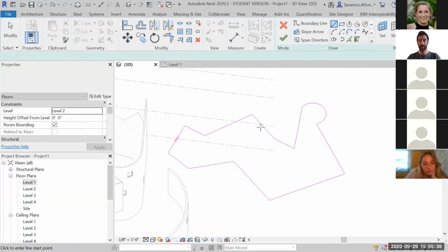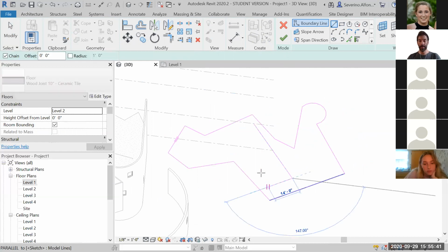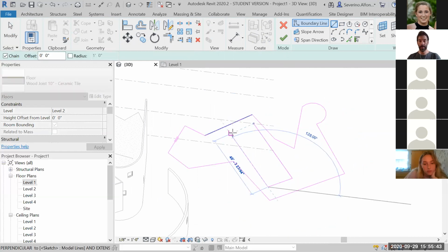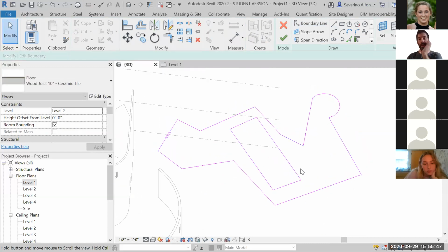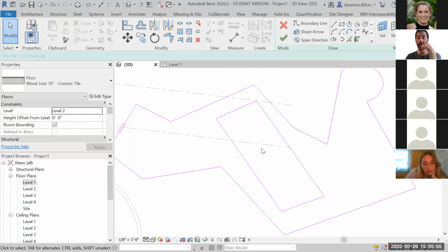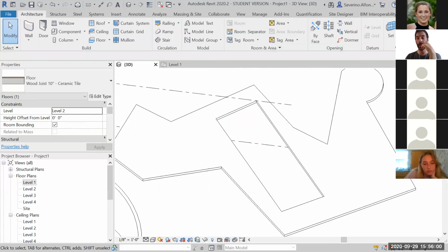I'm going to do a bit more funky opening. Okay, if my polyline, the one of the floor, has another polyline that is close inside, this means you're doing a donut in a way. It means that the center here is not going to be with a floor.